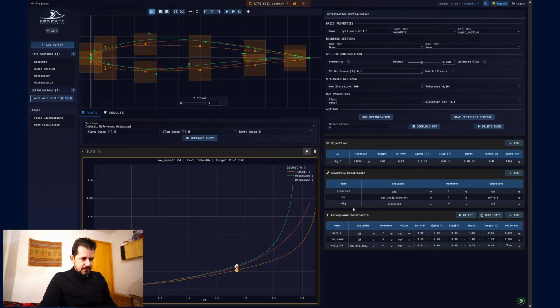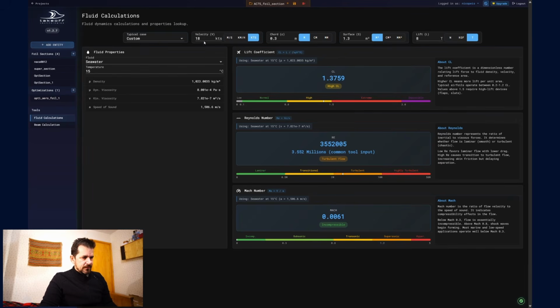And we're gonna say, so now we're gonna come here and we're gonna limit the cavitation, for example, at 43 knots. As an example, each one, then we can play a little bit with this parameter. So what is the CL we have in this condition? 0.24.